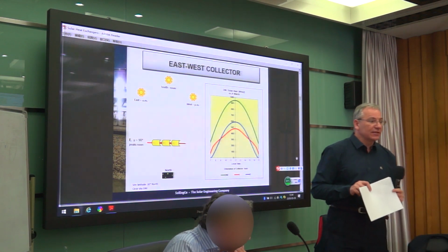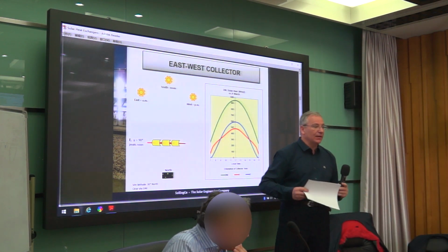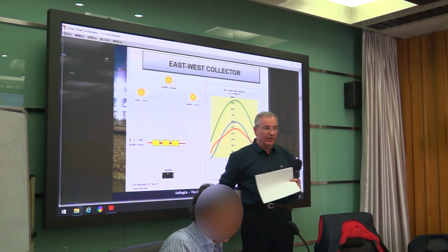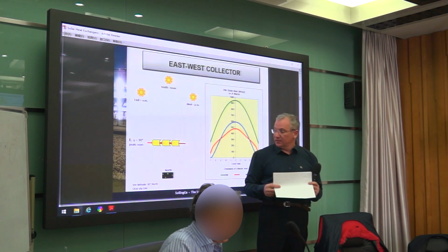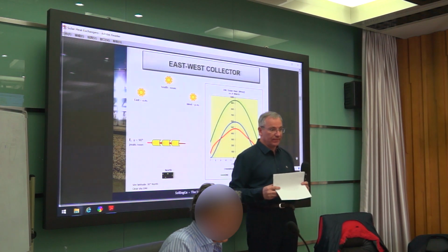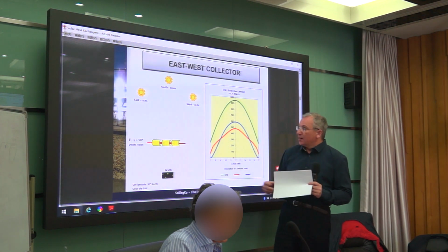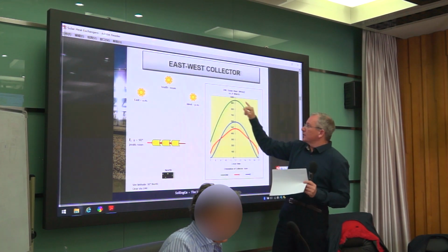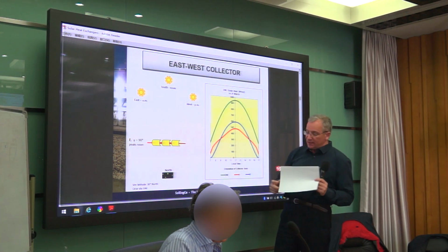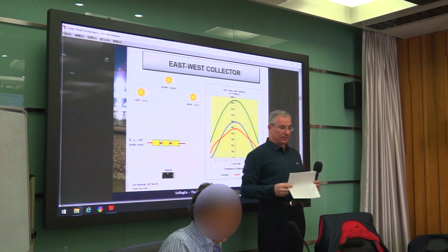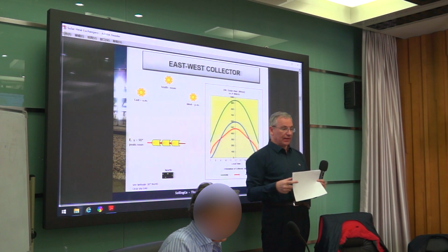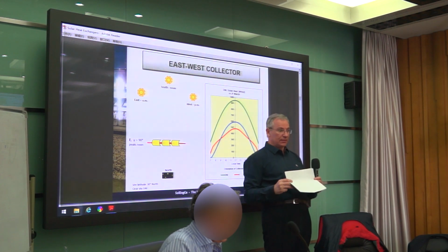Now we will do the same for the same site and the same irradiation. As you can see here, we are at latitude 30 on the northern hemisphere. All day is perfect weather, which we can also see from this line. We put the collector in this position, and the sun is coming from here to here, and we track only this angle.